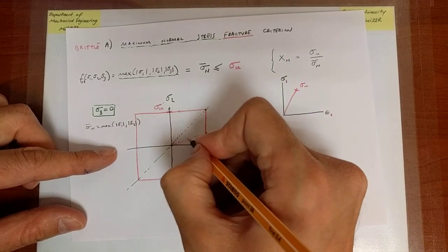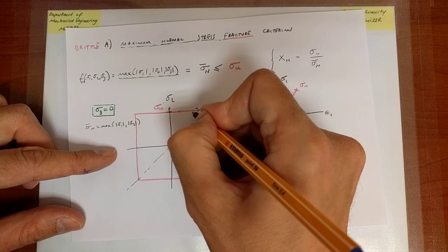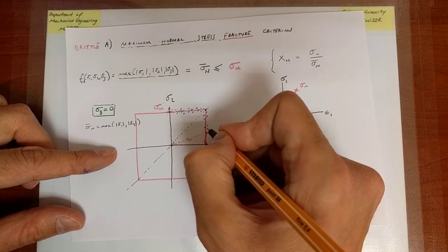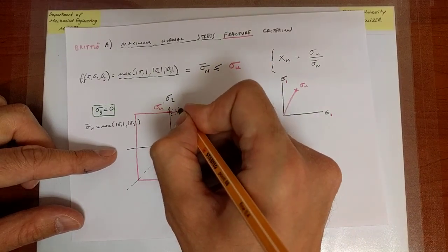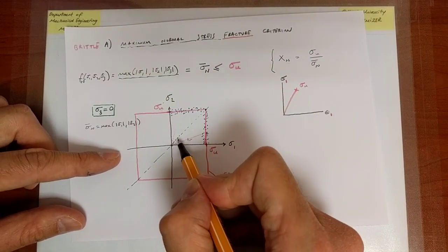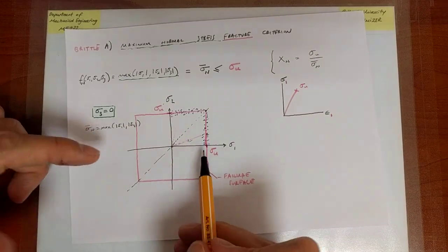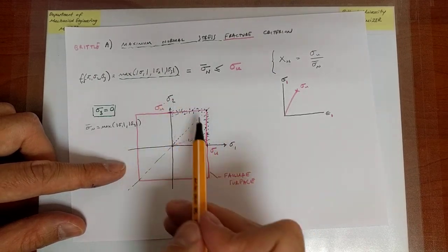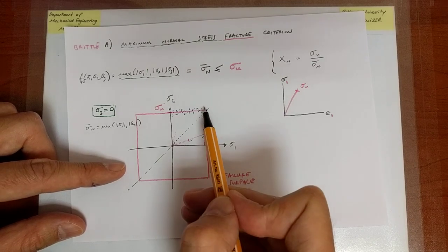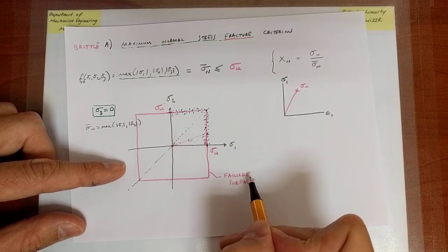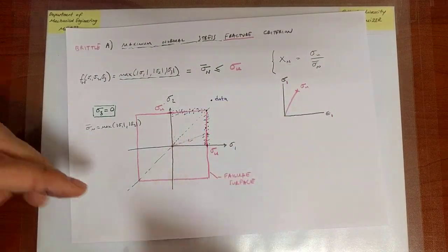And suppose you load along certain lines and you find combined stress values that lie, let's say, in the first quadrant in such a manner. There will always be experimental scatter, but what we are saying here is that when I load along the line, failure happens there, failure happens there, failure happens there. And we see that the red line, our theoretical prediction, is a good approximation of what happens in reality. So the theoretical failure surface is of course accompanied by an experimental failure surface that gives us the data.